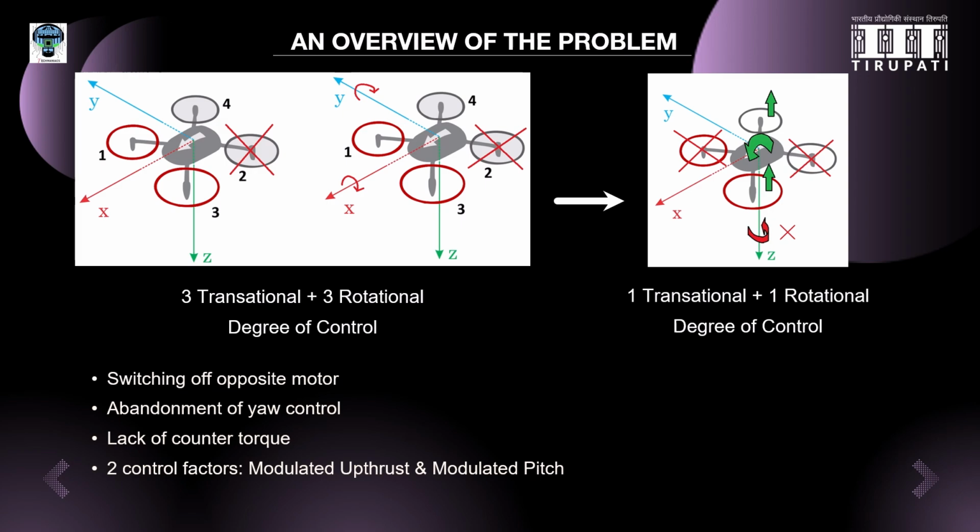This is a known strategy. As one expert notes, if the goal is simply to stay in place while allowing the craft to pitch, roll or yaw freely, it can hover even with one motor. By giving up precise yaw control, the quadrotor still has 2 remaining control inputs, vertical thrust and one tilt angle, which are enough to guide it down gently.